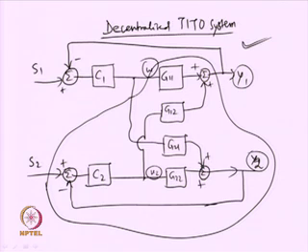So, that equivalent subsystem Q1 will now be the ratio between y1 and u1. For that I have to consider this, so I have to break the loop as well. If I break the loop over here, then I do not have this, okay. Then it will be possible to find the ratio of y1 upon u1. How can you find y1 upon u1?